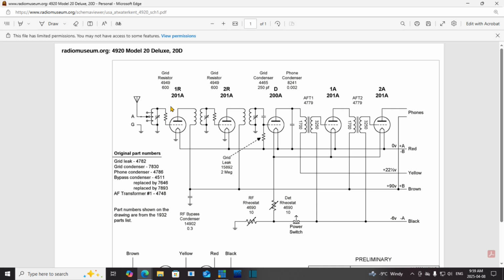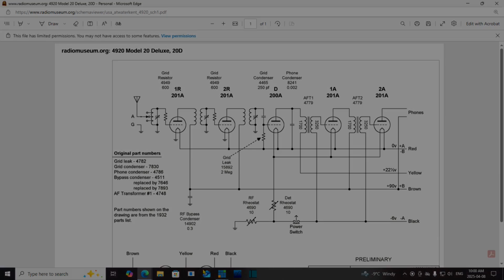Because if this is open, which it certainly appears to be open, then there's no antenna connected to this radio at any time. There's never been. Now, why would it be open? It looks like it's open because of corrosion. You can't really get a bolt of lightning through here. The bolt of lightning would go down through the coil and would burn the coil. Not likely to burn this. I think it's just corrosion that's done this guy in. Okay, that's good. 600 ohms, eh? Let's give it a try.